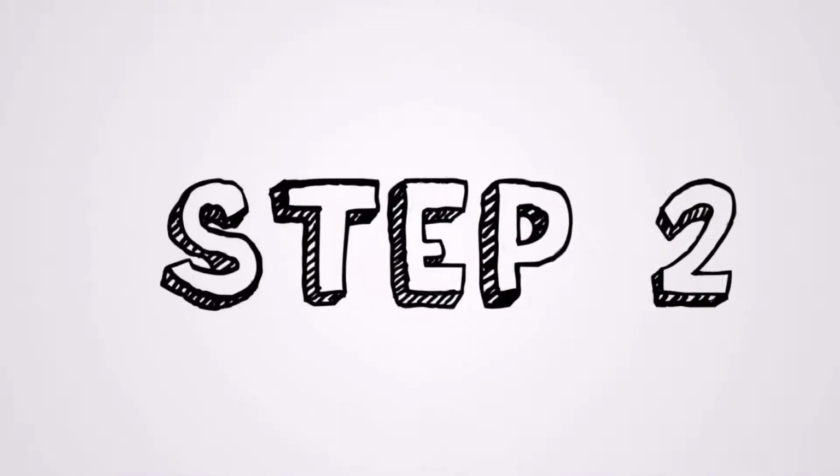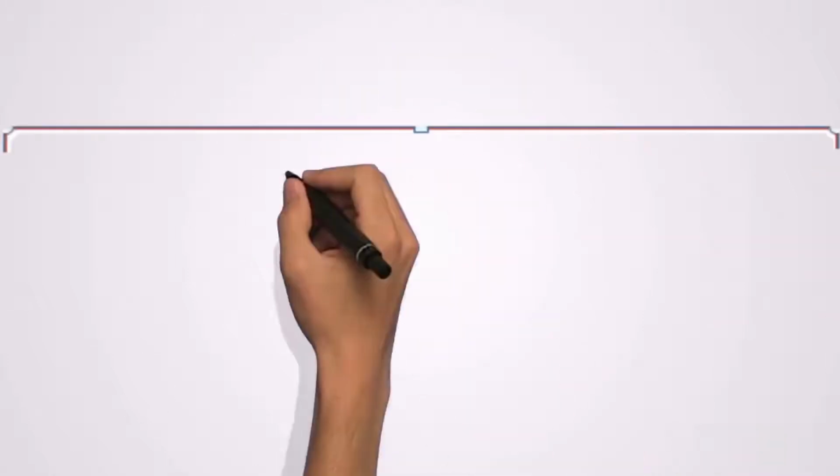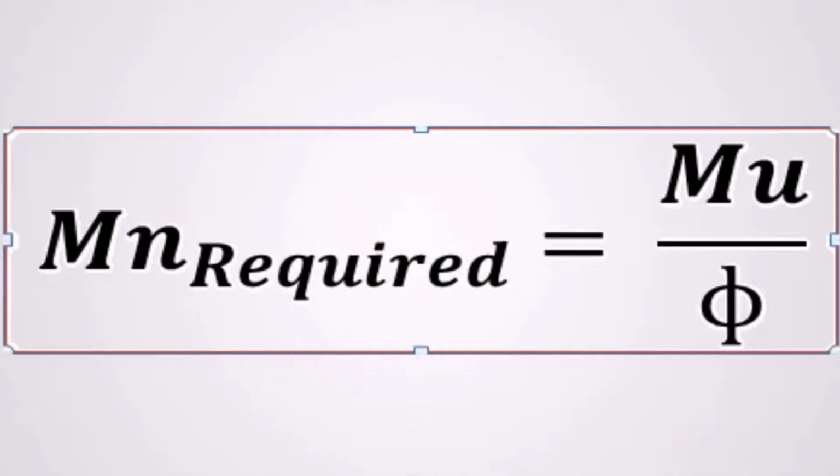Step 2 is we are going to assume phi equal to 0.90, which is the strength reduction factor, and we can compute the required nominal moment Mn, which is Mn required equals Mu divided by phi. So phi is the strength reduction factor while Mu is the ultimate moment.